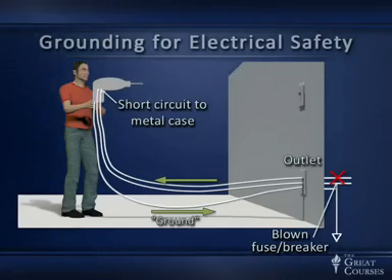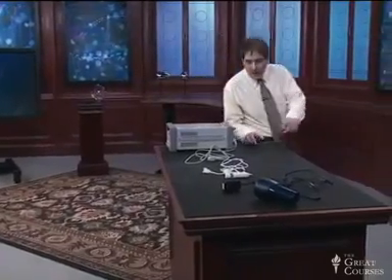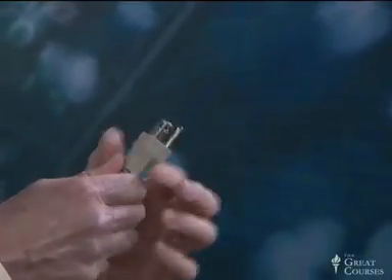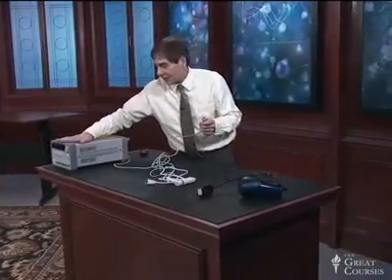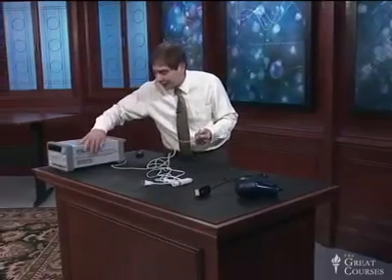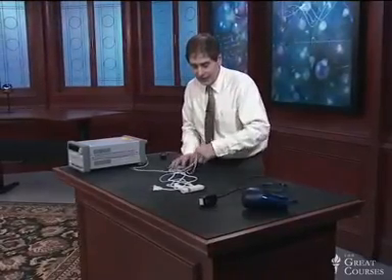So the reason you see grounding prongs, and let me show you some, the reason you see prongs like this third prong on this piece of conductor, this conducting prong, this big round one, is because all the metal parts of this power supply, the one I used to charge the capacitor in the previous lecture, all those metal parts are connected directly to this prong. And that means if anything goes wrong in here and high voltage gets somehow connected to the metal case, it will simply blow the fuse and I will be safe. So that's one way of protecting us from the danger of electric shock.